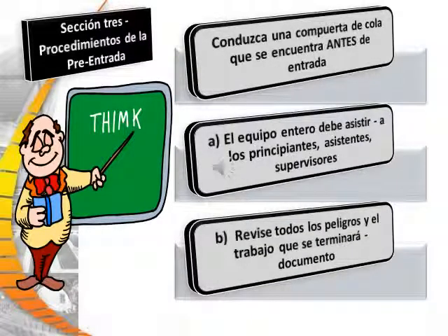Conduct a tailboard meeting before the entrance into the permit area. The entire crew must attend: entrants, attendants, and supervisors. Review all the hazards and the work to be completed, documenting everything.